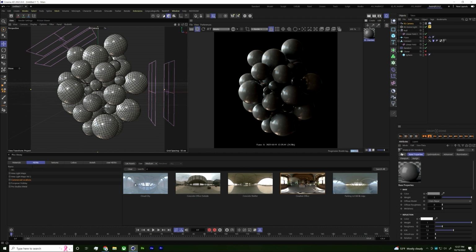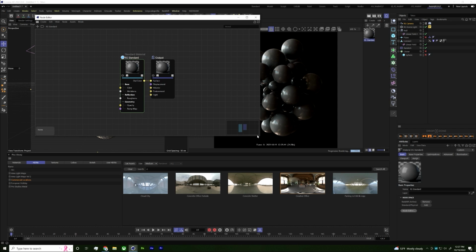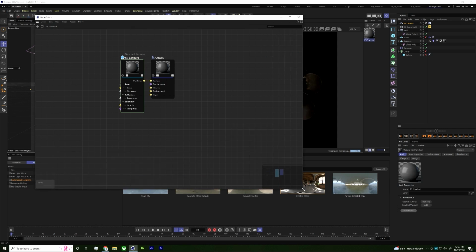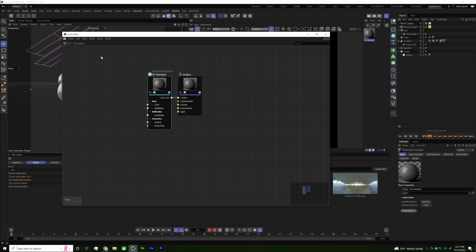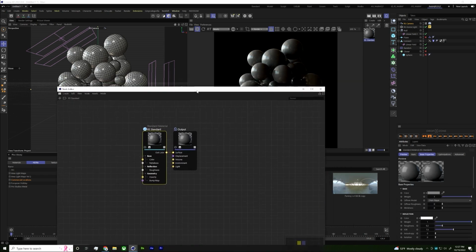So if I double click on my material and I open up my basic tab, you're gonna see node editor. In the node editor, you're gonna see some nodes. Now, if you've been a little anxious to jump in here and think these nodes are not for me, it's gonna be okay. We're gonna get through this together. It is very straightforward and not as complicated as it looks. In fact, all you need is a couple nodes to get really dangerous here, especially with vertex maps.